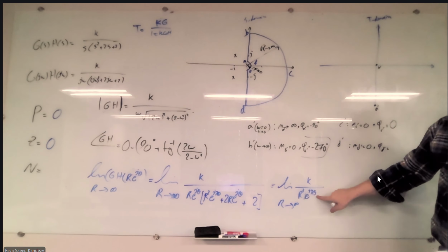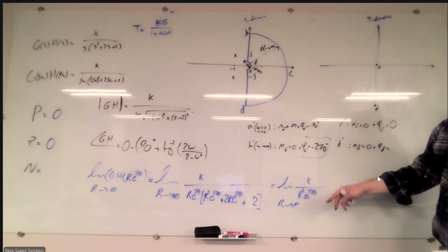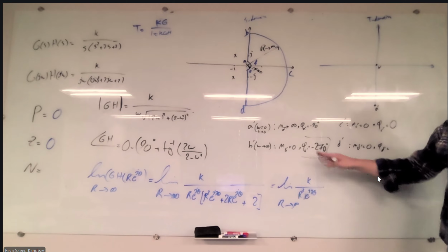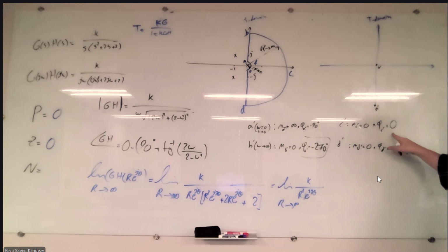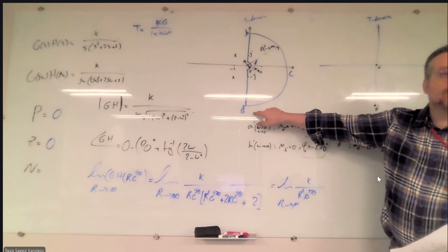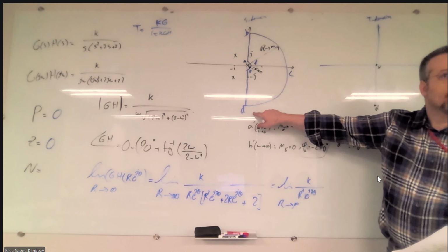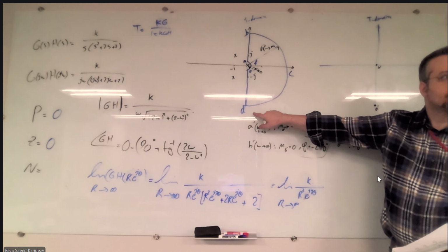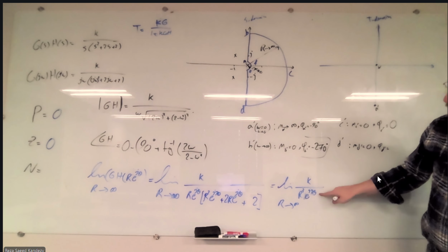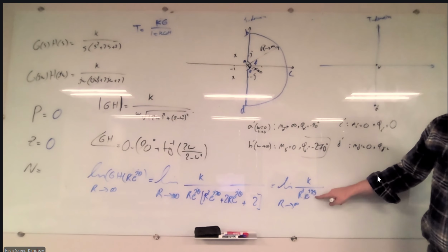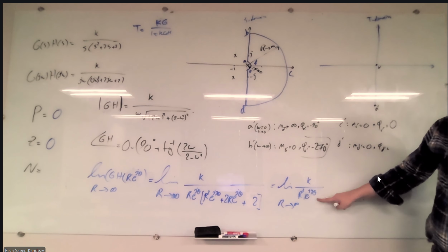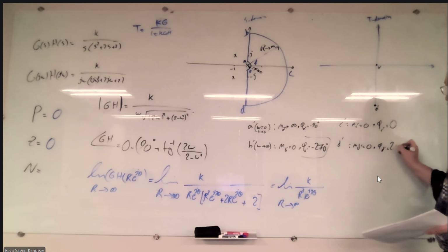We put 0 at theta. 3 times 0 is 0, so the phase of the denominator is 0, and eventually the overall phase becomes 0. For D, the phase is minus 90. If we put minus 90, we have minus 270 in the denominator, the overall thing becomes 0 minus minus 270, which is 270.